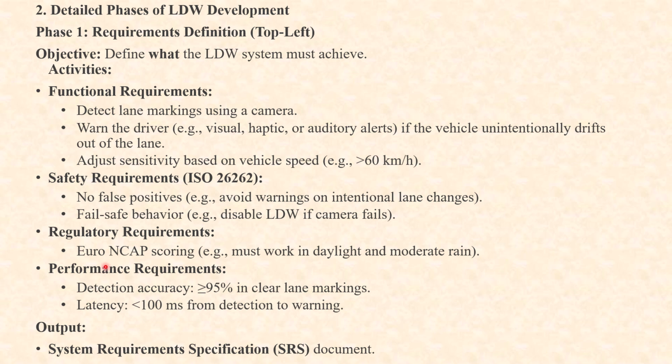Next, some regulatory requirements, such as Euro NCAP scoring: it must work in daylight and moderate rain. This is a European NCAP requirement, and the daylight has some candela units. For example, it should work above so many candela, or work under so many centimeters of rain.